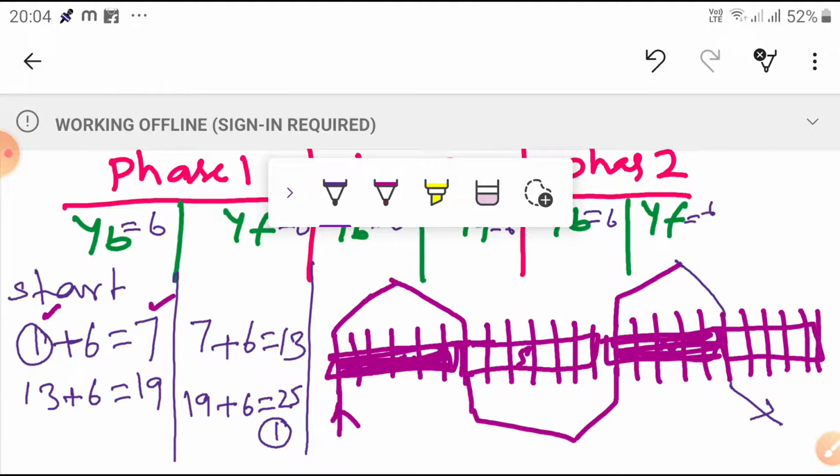Dear students, please remember that. As usual, I connect 19 plus 6 and get 25. There is no slot number 25, there are only 24 slots, so 25 minus 24 is the first slot. The first slot is already filled, because in an AC winding there is no closed winding path. Hence you have to take one precaution: instead of this 6, you add one, so instead of 6 you change to 7. Why? Please listen once again.